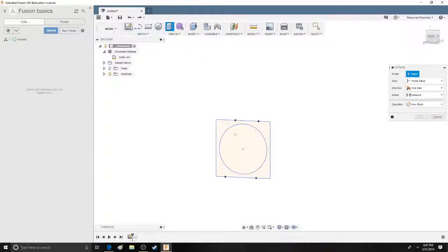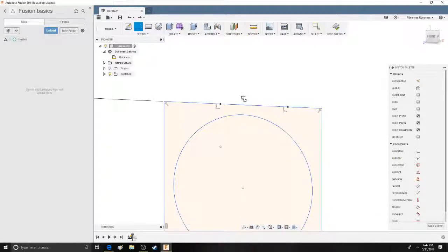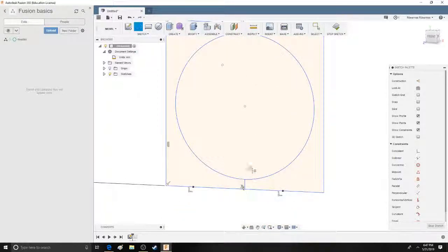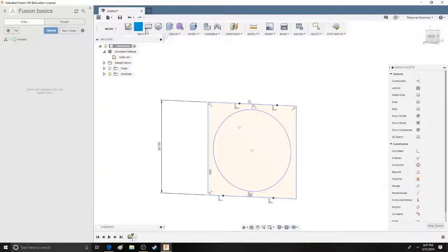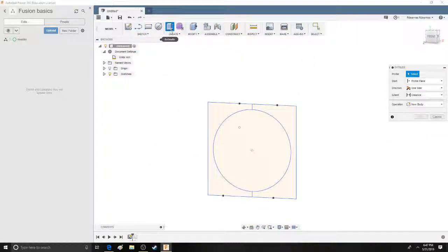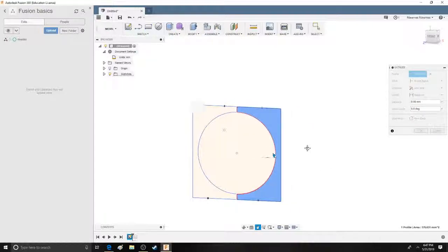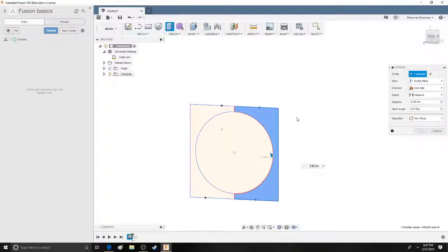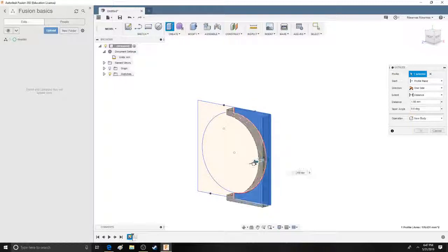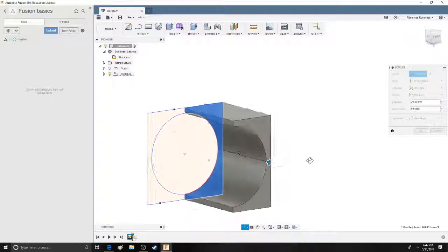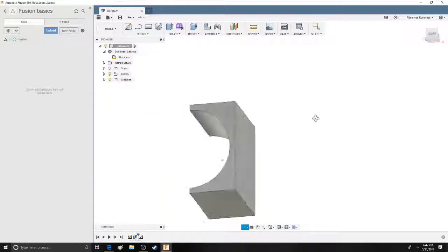So, let's say you only want to make sure that there's a certain segment. You just close it off using a sketch. So right here, I will close off this by connecting into that, just using a small sketch. So let's say I only want this side piece. I'll go over to extrude, which you can also press E to instantly access. So you can go from select to E, and you can instantly extrude. You can click on just this piece now that it's segmented, but it also needs to be completed, and extrude outward. And there you go. You have your half piece.